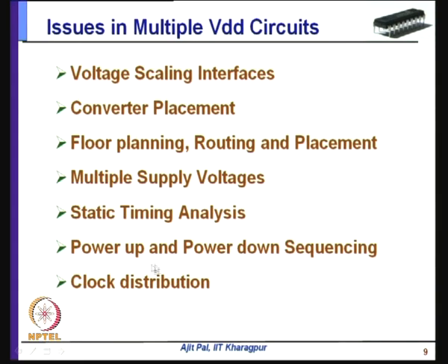Then comes the question of clock distribution. We have seen that the circuits are operating at different voltages and frequencies. So, the clock has to be distributed, and if multiple clocks, I mean different frequencies, are to be applied, that also has to be distributed properly. So, these are the different issues to be considered whenever we go for multiple VDD circuits.